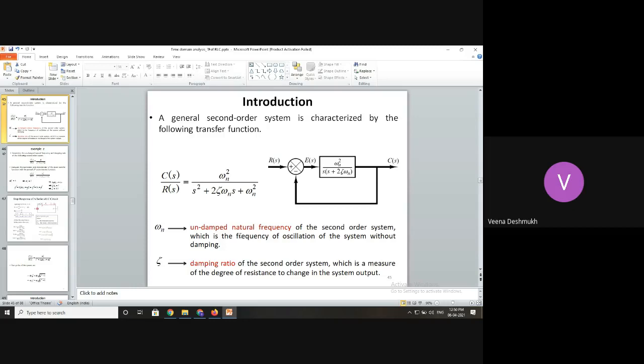Because when we start communicating in S domain, we always talk in terms of S, roots of the equation, poles or zeros. But what are these poles and zeros? Always try to visualize how they are related to our basic components R, L and C. I am giving all those equations in the slides. So always try with RLC so that you know their impact in time domain. We can very easily relate to time domain because RLC are the components we have used in our circuit and we know where exactly they are placed.